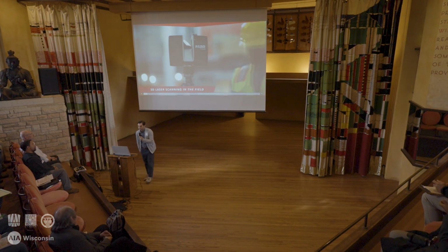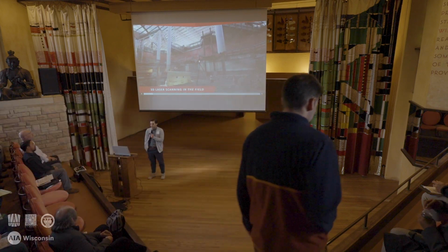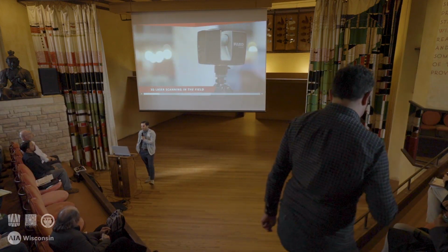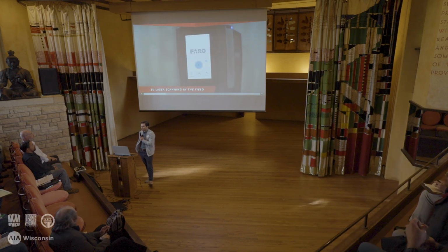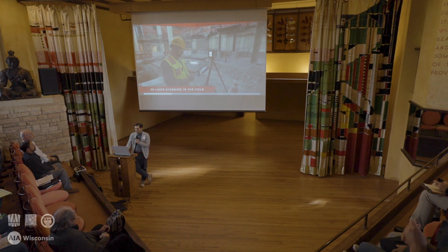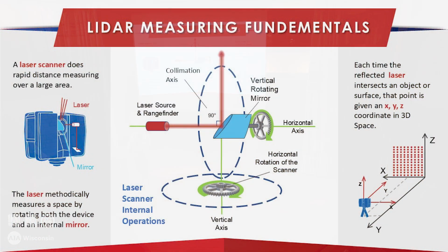But this is the device here. It's about the size of a shoebox, sits on a tripod, and it's emitting 2 million of those single point measurements every single second. And so anything that you can see from the scanning device is being recorded as an XYZ coordinate in space. And that mirror that you see spinning in the middle of the device, that's what it uses to capture everything in the vertical axis. And so it kind of strategically goes through and maps out a single point cloud from a single scan.